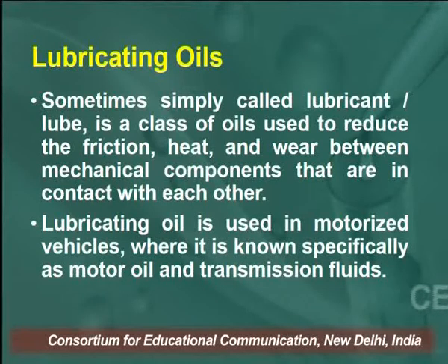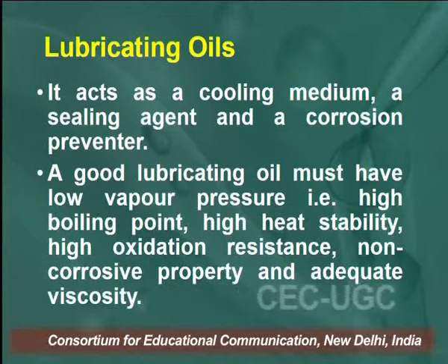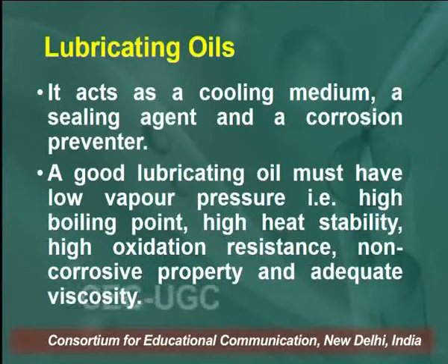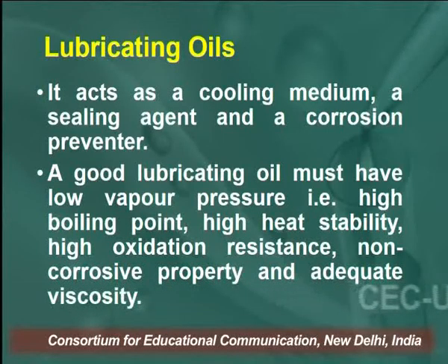Lubricating oil is used in motorized vehicles where it is known specifically as motor oil and transmission fluids. It acts as a cooling medium, a sealing agent and a corrosion preventer. A good lubricating oil must have low vapor pressure, that is high boiling point, high heat stability, high oxidation resistance, non-corrosive property and adequate viscosity.